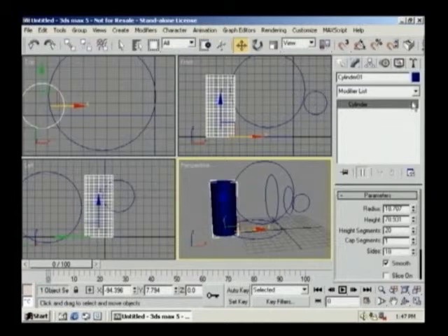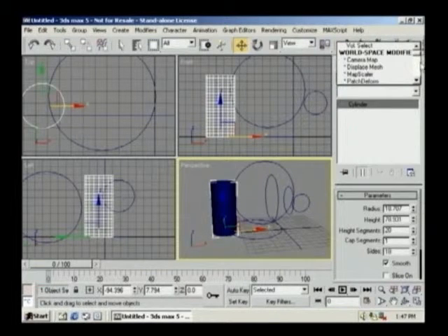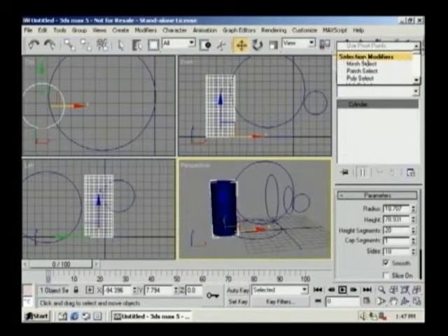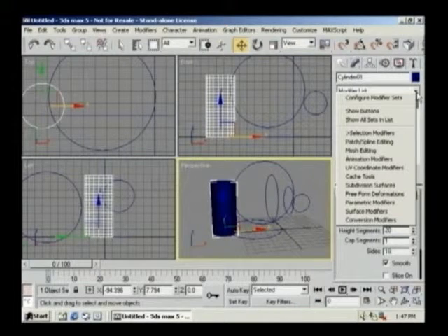Back on that configure modifier list, go to that flyout again, and you'll see a list of all the predefined modifier sets that came default with 3ds Max 5. The top one being the selection set. And you'll see a little marker to the left of that name. This is indicating that this set will appear on the top of the modifier list in alphabetical order. If I click on the UV coordinate modifier list from this flyout, now we go back to the list.